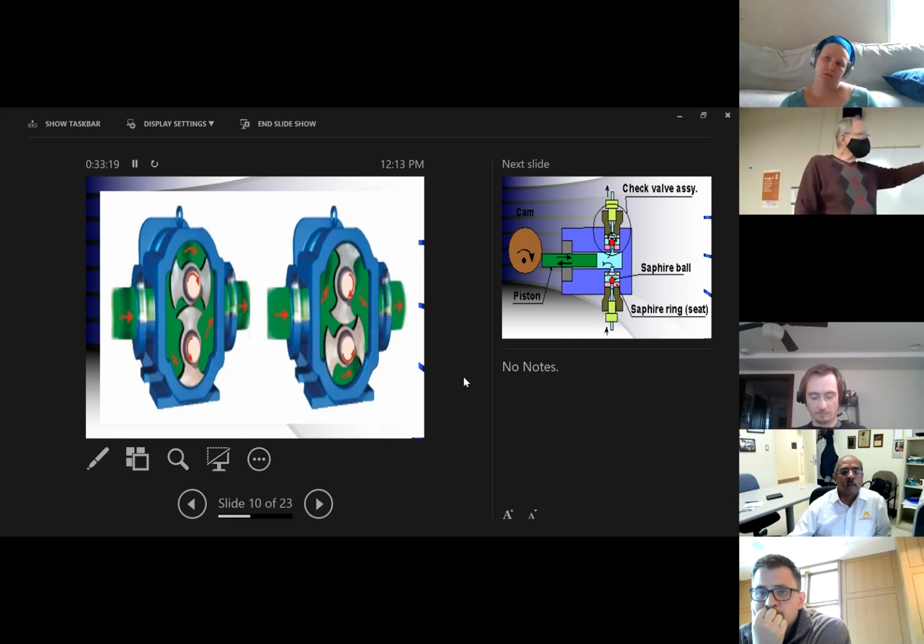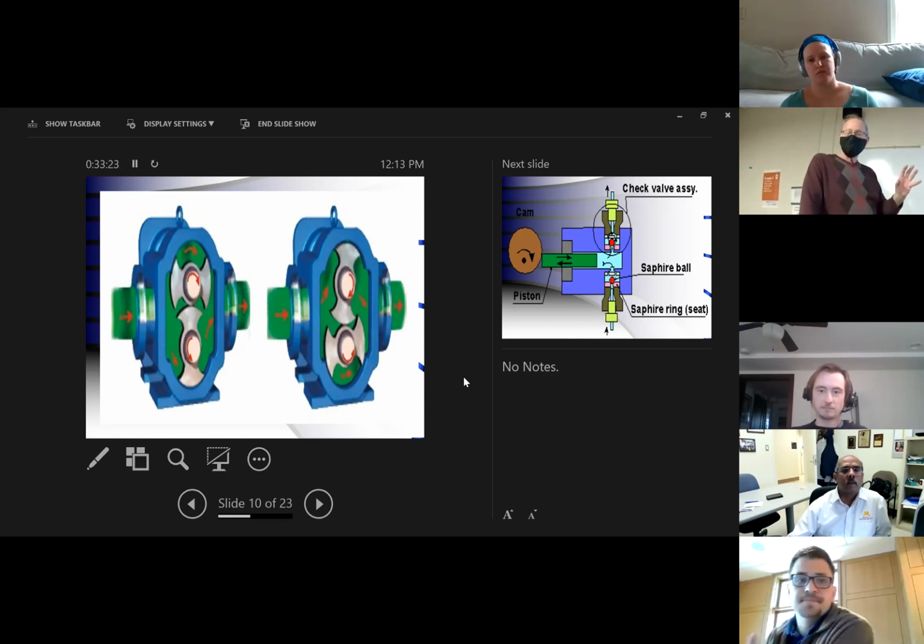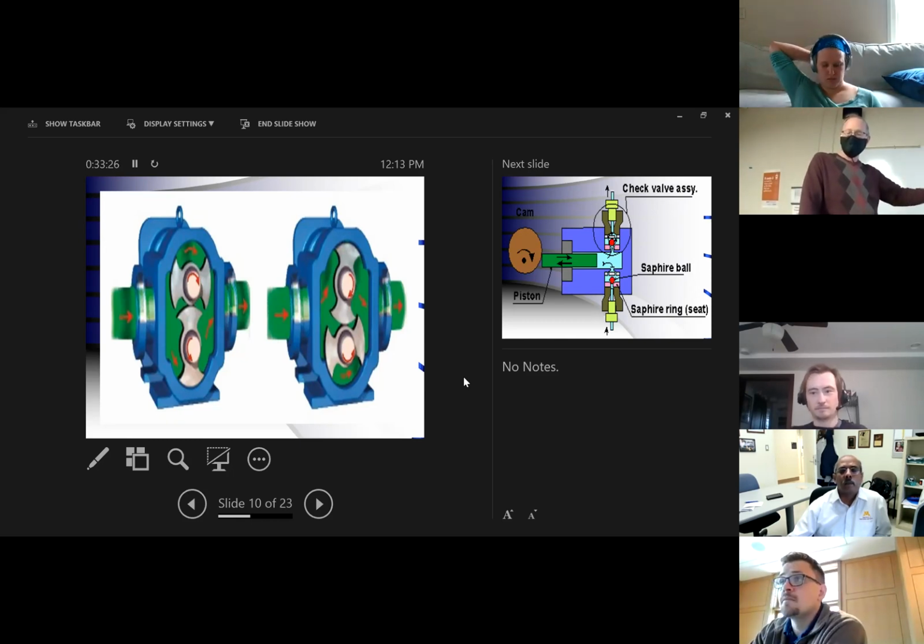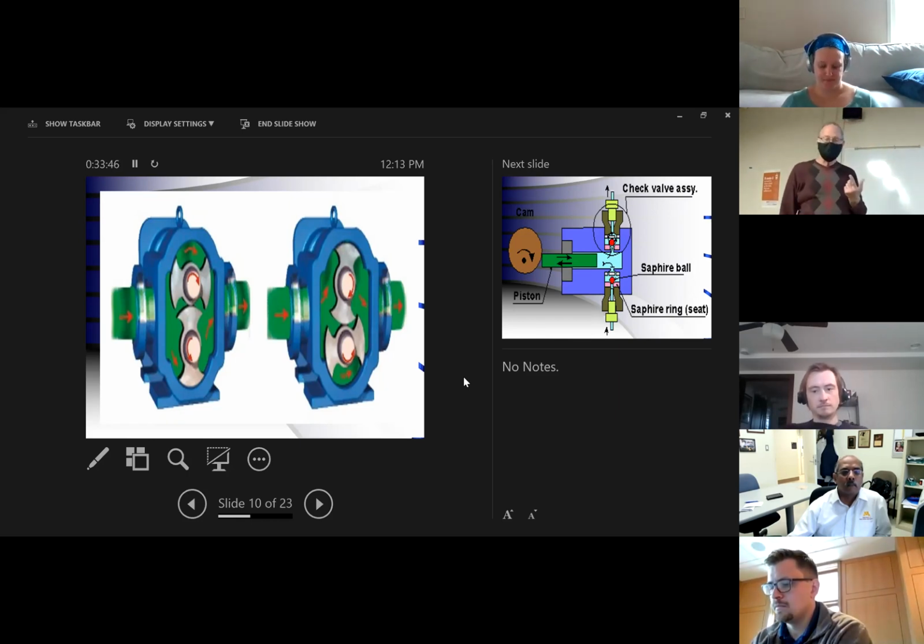That's why these pumps can cost you some serious money, because as this liquid flows in, notice it's either transported up or down. Notice these 2 lobes are turning. As they move, they basically are creating, if you want to think of it, pockets of liquid. And as that liquid fills the front cavity, it's moved to the second cavity and then pushed out. When you have a 4-lobe system, you have more cavities. But the whole idea here is tight machining, tight tolerance in there. One little thing to file away in the back of your minds is that obviously with time, these will wear a little bit.